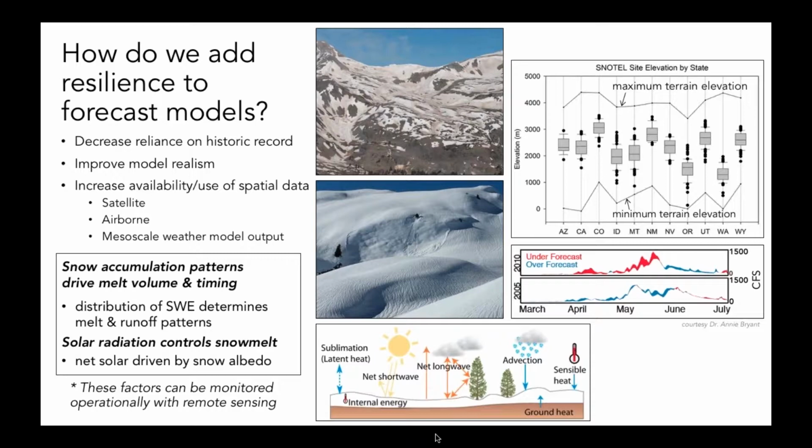And there's two basic types of operational forecasts. One is a total runoff forecast, so an April through July aggregate volume, and that is generally conducted by regressing April 1st snow water equivalent measurements from a station network on stream flow with a 30-year minimum period of record and saying, okay, April 1st snow water equivalent equates to this stream flow volume in the summer. Shorter term forecasts are typically based on temperature index models. So we start with an accumulated volume of snow, look at the measured air temperature, and then with a calibrated model, predict how much snow is going to melt and run off.